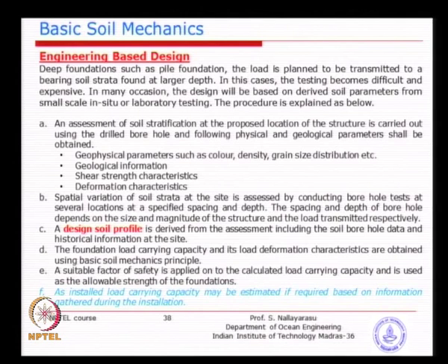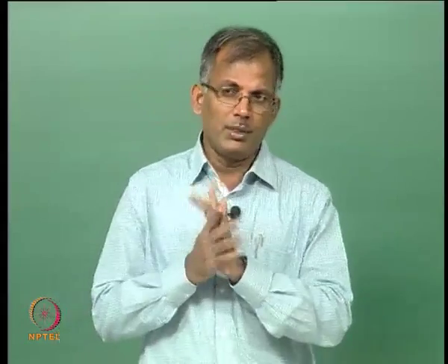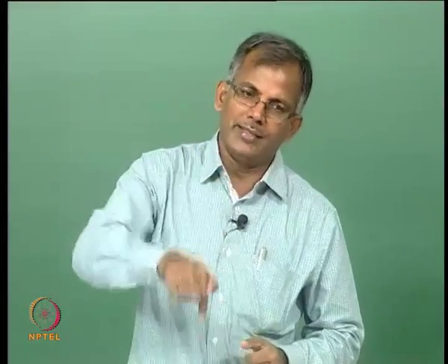So, you do testing to establish the relationship between stress and strain. Once you do this for one particular location, you then look at the spatial variation, if you have more information. If you do not have information, then you are going to rely purely on one borehole. That is why most of the time for offshore structures we do the borehole exactly at the center of the platform itself, so that the distance to all 4 piles is equally distributed. The risk involved in installing a pile is also equally distributed, is it not? So, all 4 will have the same equal risk, but of course, if the soil varies within that 50 meters, as I mentioned earlier, it is bad luck.